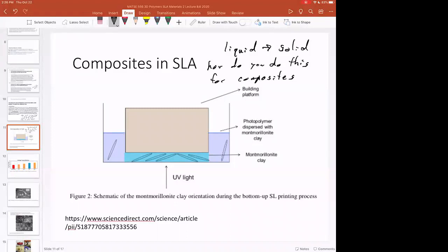There's continuous fiber composites where we saw the mongoose laying down fiber uniaxially or winding a fiber around a mandrel, like how they make golf clubs or something like that. But there's also particle-based composites that we talked about. And so in general, SLA, you can only really approach particle-based composites with some sort of aspect ratio. So in general, these are particle-based composites.